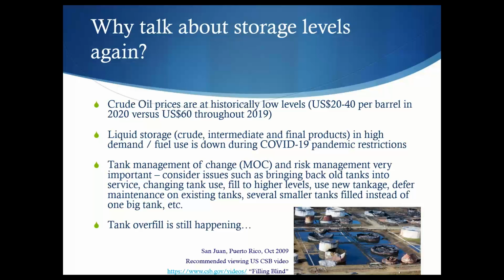They didn't have independent and separate safeguards versus the control measures, such as the high level and the automatic overfill prevention system weren't independent from each other. They also talked about procedures, management systems that had failed, and human factors in terms of the drain bund valve being left open. So basically people weren't learning between those two incidents, and even now people tell me they don't know about this Capeco incident or even Buncefield, so it's worth reading up on those things and acting on the findings.